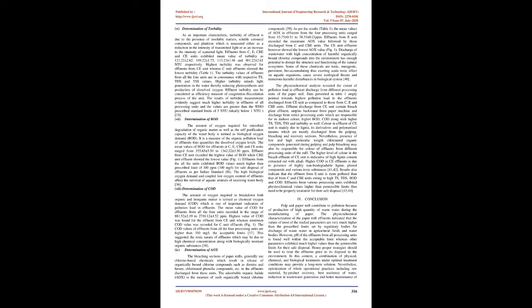Visibly, the effluent had a yellowish brown to dark brown appearance at the time of sample collection. Data presented in Table 1 revealed that CE effluent exhibited the highest color value, followed by E and CBP stages. The darkest color of CE effluent of the paper mill may be due to the presence of some amount of black liquor. The color of effluent has an impact on its aesthetics, transparency, and gas solubility.